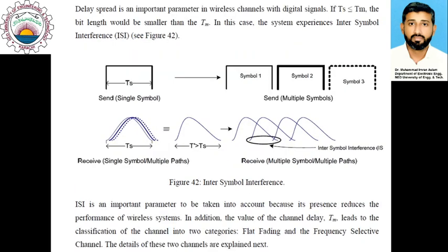Okay, now we come to the discussion regarding the importance of calculating delay spread, because we now understand that when the signal propagates through the wireless environment, it will reach the receiver with different delays, and eventually the overall width, or time duration, of the signal will increase because of this delay spread. So whatever symbol duration you have at the transmitter side, you would not have the same symbol duration at the receiver, because of the delay spread which occurs from propagating through the wireless environment.